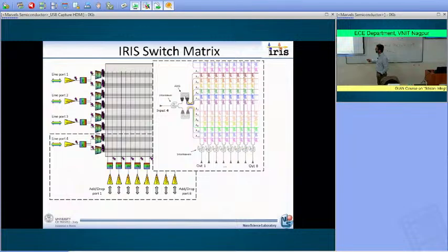Okay, let us concentrate on the single input. So we have one direction. Here we have a grating coupler, and by using this grating coupler, we get the signal coming from the fiber. On the single fiber, we have up to 12 different wavelengths traveling, and we need to have here the grating that is able to couple any of those 12 different wavelengths to the input line. And then here is the first function that we have implemented, a function that is called an interleaver. I will tell you what an interleaver is in a while.